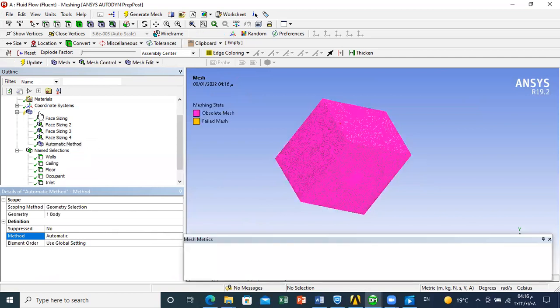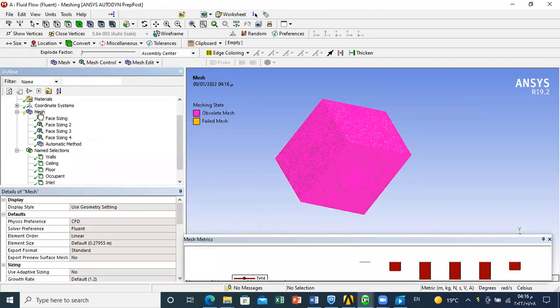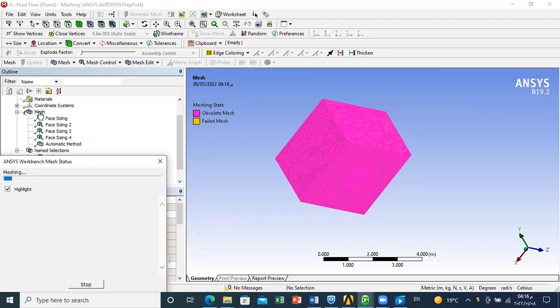So in general, it's trial and error in the meshing enhancement quality. You have some known strategies, and decreasing the face size is good. We should avoid sudden change in sizes for surfaces that are close to each other. So you can play with these techniques until having a mesh that is satisfying you.